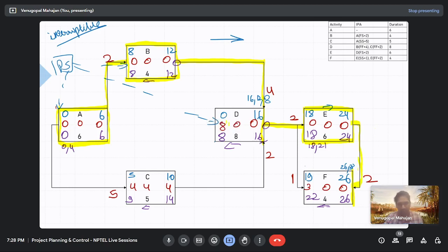So total float of activity D is wrong. Yeah, 8, that's what I am telling you. You guys didn't help me correct the values. This would be how much? 3. So if the question comes, what is the total float for activity C, or which kind of float exists in activity F, you can say that it is total float and start float. What is the value of float in activity D? Start float in activity D, 8.